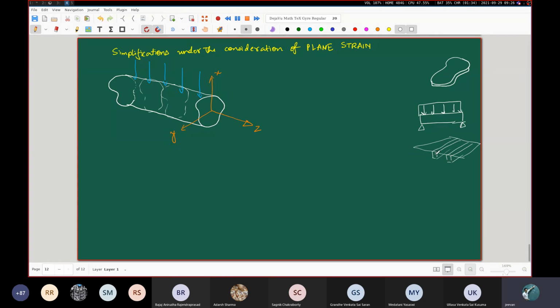the distribution of load on this beam is going to be more or less uniform. So in that kind of a situation, it is under plane strain. And please don't think that one or two people standing on the floor is going to make a humongous difference. It is only going to make a few percentage difference to the loading on this beam. It hardly matters. 1 or 2% standing there, or even 10% standing there, they have negligible weight compared to the weight of the actual floor.